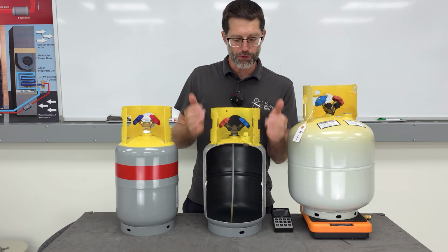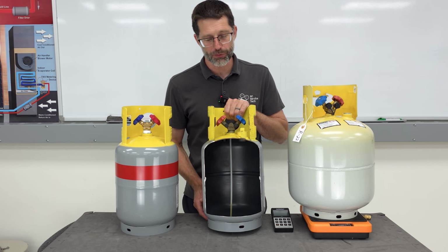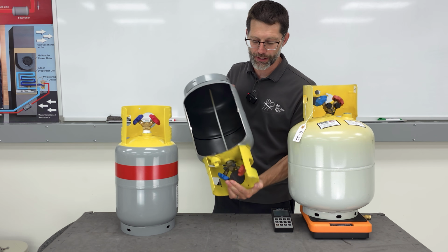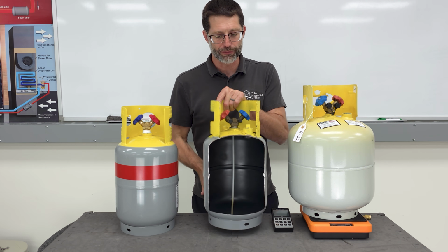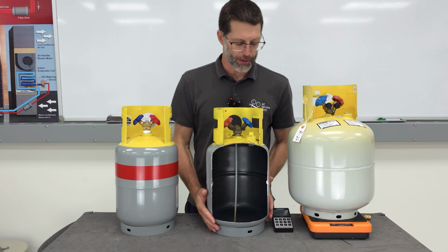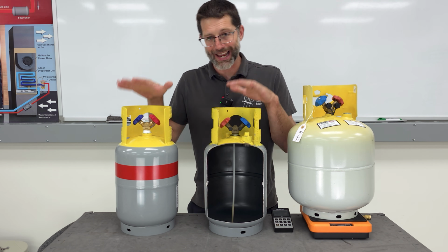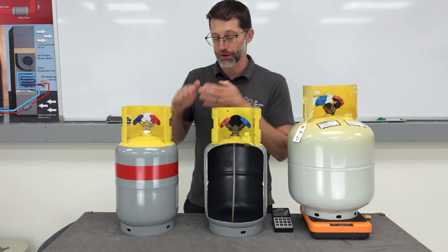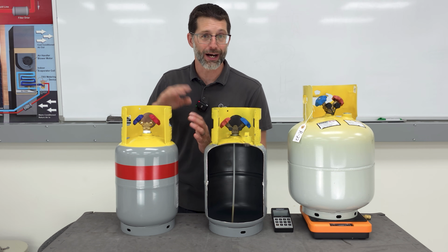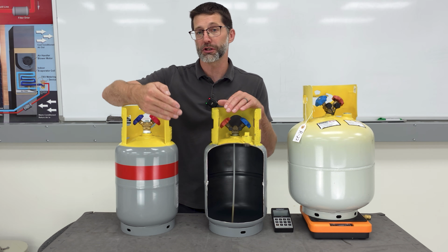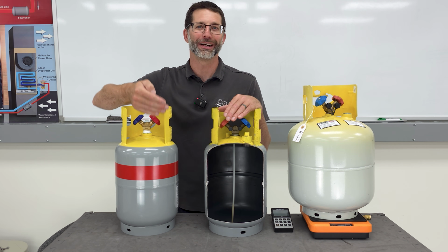But a lot of times we're just recovering right into this vapor port. And some people even flip the bottle upside down as they're recovering and put it right into the vapor side. So it just depends on how effective your recovery machine is. But the biggest thing is we need to prepare these bottles and make sure that we don't get any air into the bottle, because if you have air mixed with the refrigerant you're trying to put in, you're going to have excessively high pressure. Your recovery machine might not even be able to push that high of a pressure into the bottle.